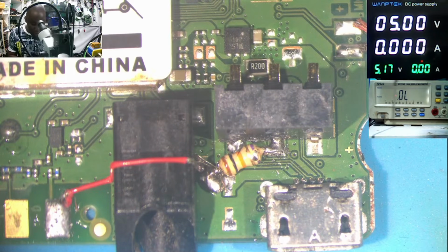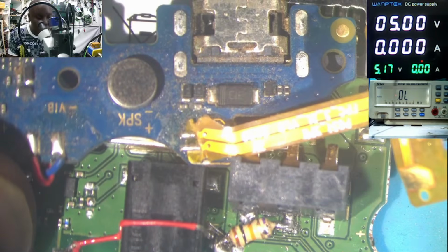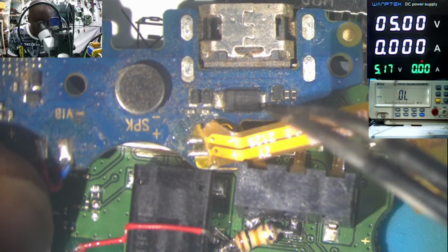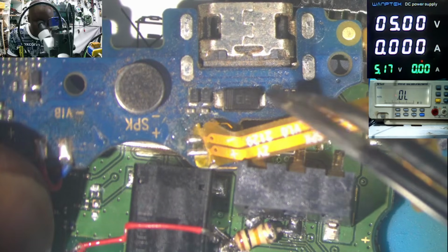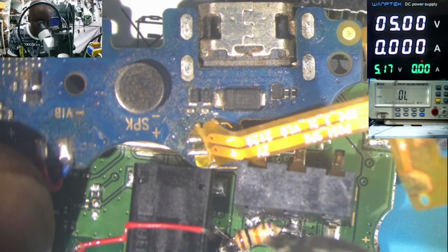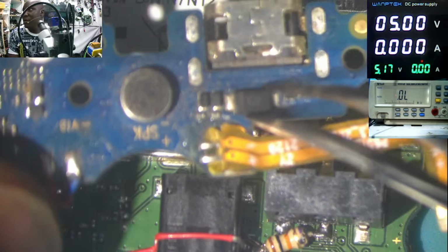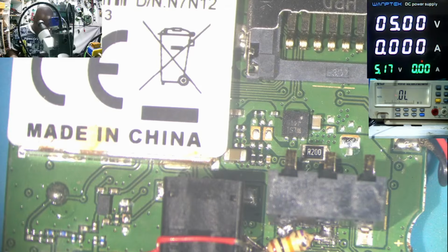Or you can use an external diode. You can use this diode. You can connect two wires here, one on the middle pin, and then the other one to ground. If you don't want to use this 10 kilo ohm resistor, you can use these protecting diodes. You remember this diode? It will do the job. Now maybe we need to insulate that.